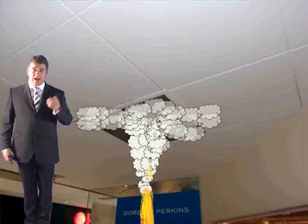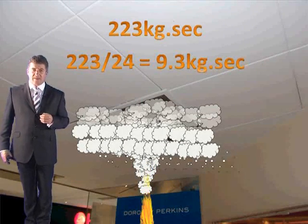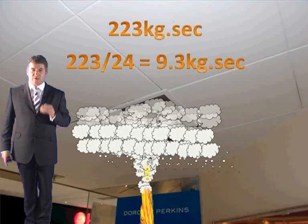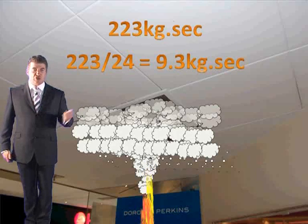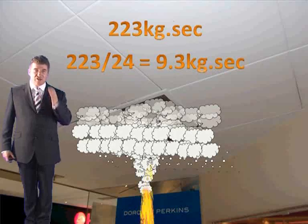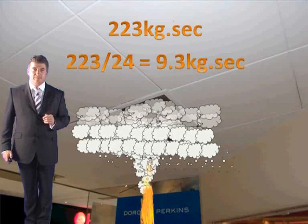What you need to do now is make sure that smoke is not going to leave each ventilator. So what you need to do is work out what your mass flow rate was, which we had earlier, and divide that by the number of ventilators that are extracting. Now our mass flow rate of smoke was 223 kilograms a second. If you divide that by 24, you've got 9.3 kilograms a second per ventilator. That's how much will be going out. We've got an mcrit much higher than that. So in this case, it does satisfy the plug holing check. It's very unlikely to plug hole.